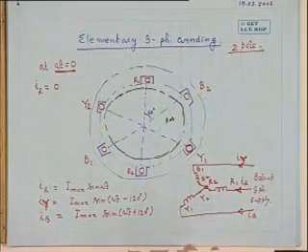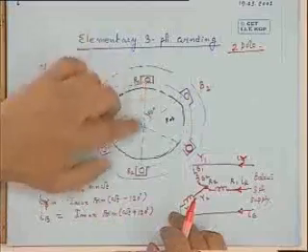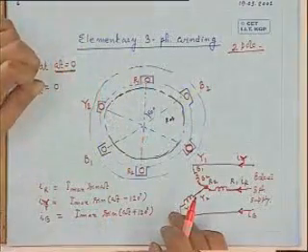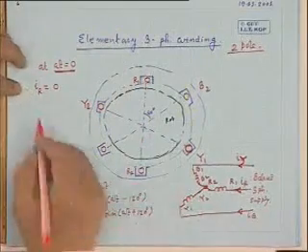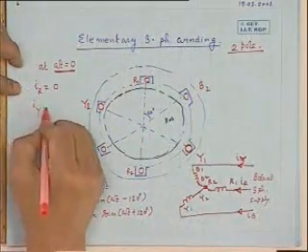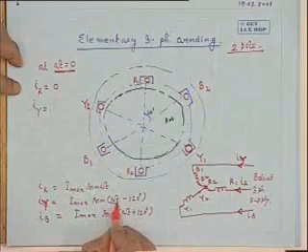See, I want to find out what is the resultant MMF distribution along the air gap of the machine. So what I will do is, I will consider several instants. Suppose at omega t equal to 0, let us take a photograph of how the currents are distributed in the conductors at that instant. Let us freeze that one at omega t equal to 0. So what should I show in R1, R2? Nothing, because at omega t equal to 0, IR is 0.